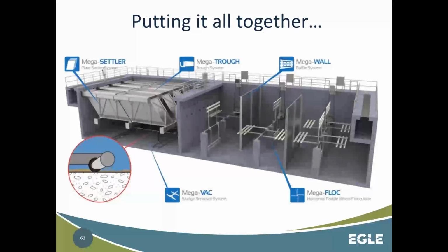Also, in some situations, you may have 2 of these treatment trains directly next to each other in parallel. And what can happen is sometimes you can use the same drive to operate both basins. So there would be another basin just behind this. You might have one drive that's turning both of these, this stage of the flock basin, and for each one of these. I've seen that be pretty common, I suppose.